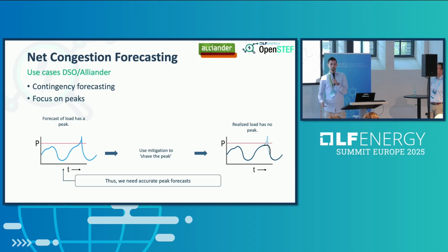When we add these new customers to the already full grid, we will have moments where the grid will be overloaded at some point. So what we do is forecast these points into the future, 1 or 2 days ahead. There you can, for example, see that on the second day there is a peak, which basically means the load will exceed the limit of this asset.